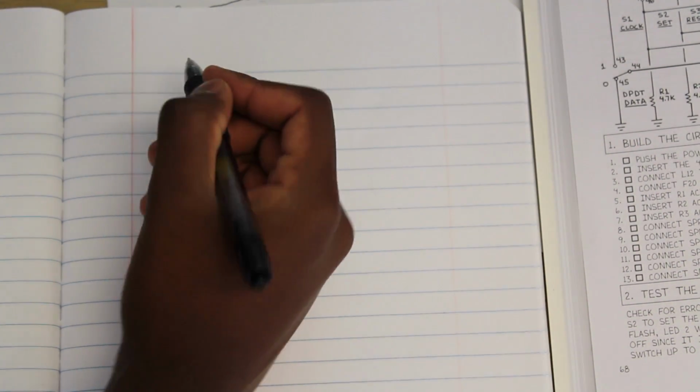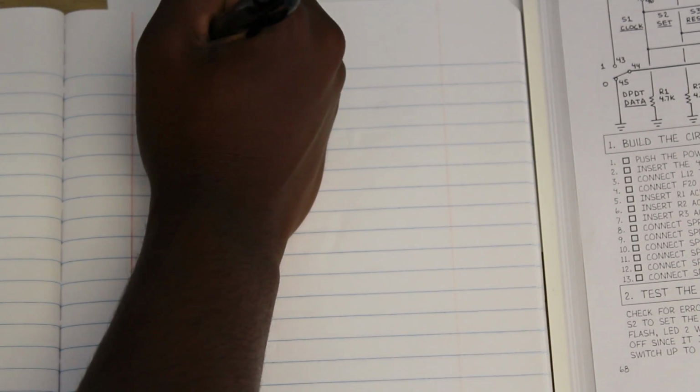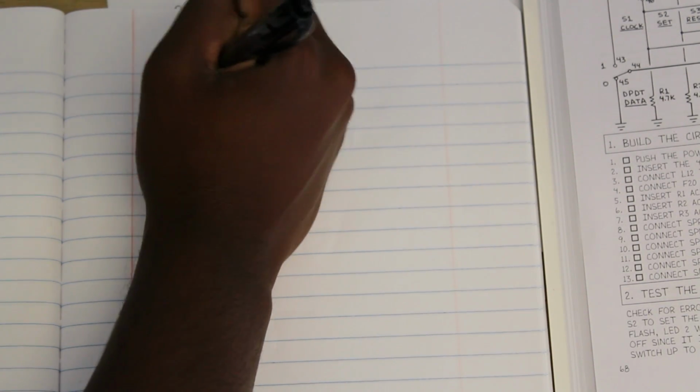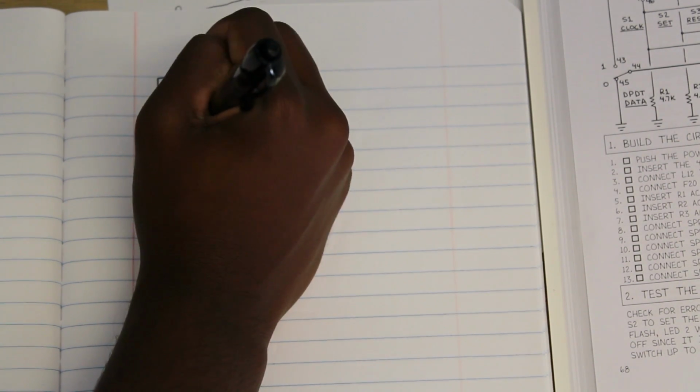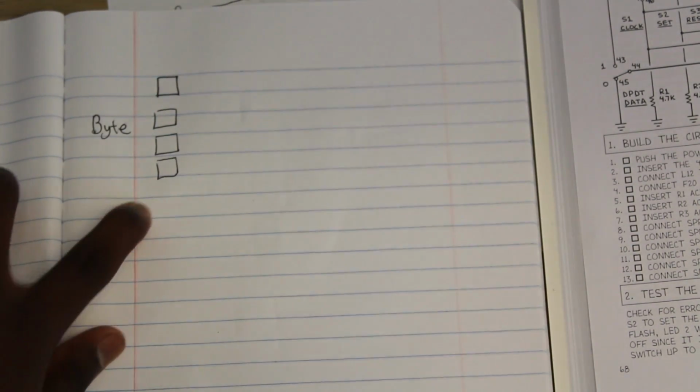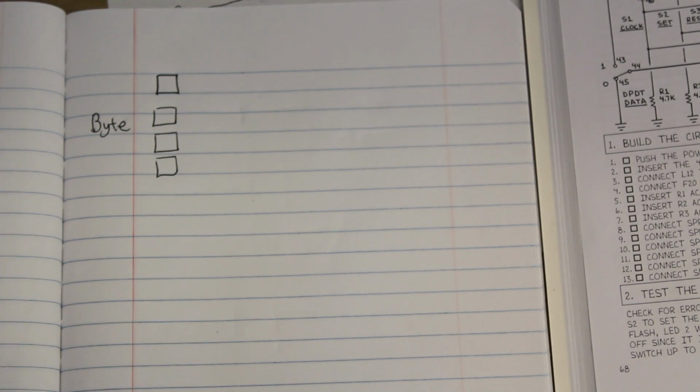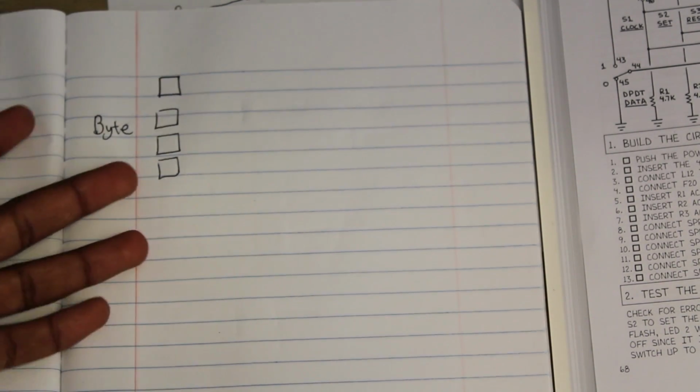But for our ALU, we can get that done in 1 IC. Although you could expand that out to the entire board like we had before. Not important though, space is not really an issue for us. So what we're going to do is we have these blocks. Each block is equal to 2 bits, so we're going to need 4 of them, and this is going to be equal to 1 byte. So 1 byte of flip-flop IC is going to be equal to a single number.